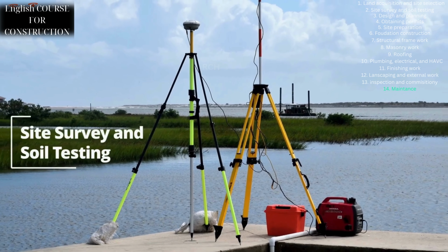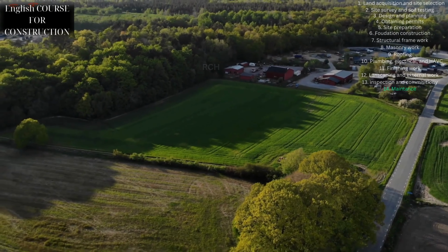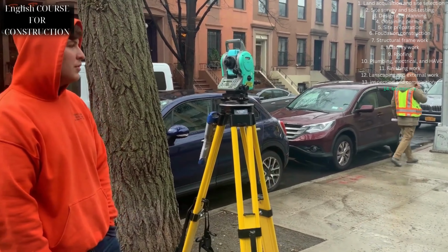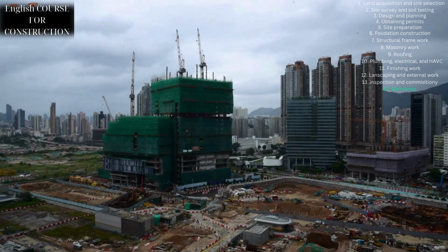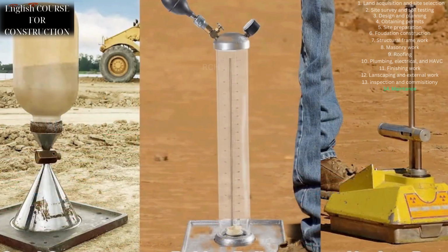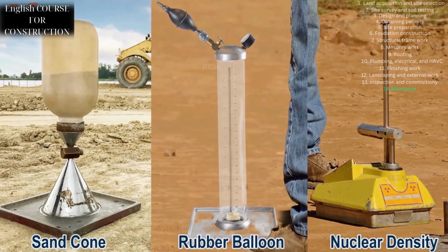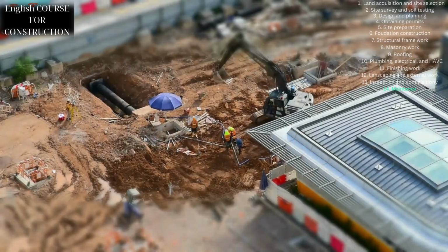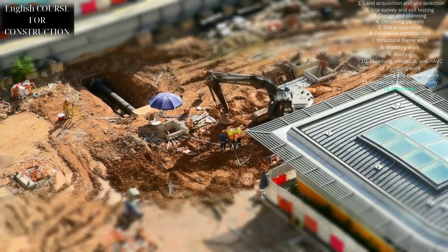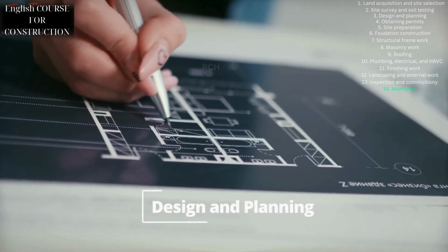Step 2. Site survey and soil testing. Once we have our land, it's time to gather essential information about the site. This involves conducting a detailed site survey and soil testing. A site survey provides information about the land's topography, boundaries, and nearby utilities. Soil testing, on the other hand, helps us determine the soil's load-bearing capacity, which is crucial for designing a safe and stable foundation. As a civil engineer, understanding the site and soil conditions is fundamental to the success of our project.